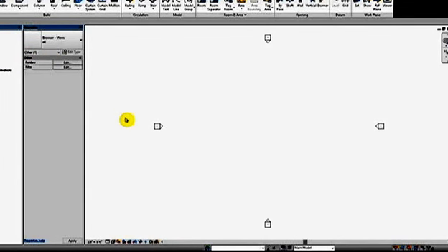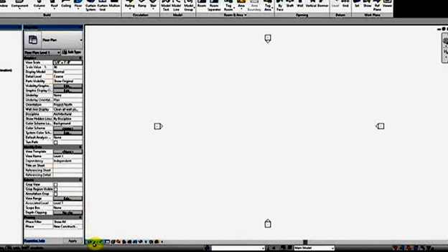All right, the next thing to cover is this little toolbar down here. These are icons that allow you to quickly change various view settings without having to go into the properties of that view. You can quickly change the scale, the detail level, you can hide elements, you can reveal elements that were hidden, etc. We're not going to cover them now, but these are just quick view changes that will come in handy while we're modeling.